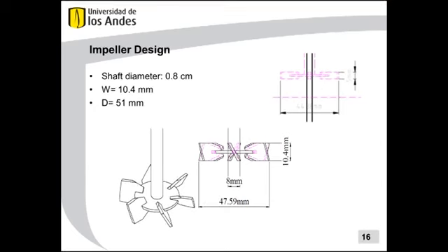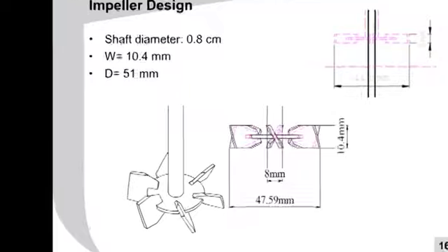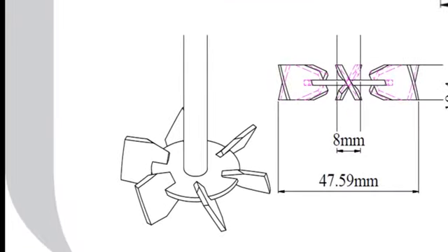The designed impeller had these dimension restrictions, so the geometry designed was similar to the Rushton turbine, but varying some components, like the vane geometry and inclination. Despite the many studies reported, impeller design is still a very empirical process, so we had to be creative. As the vane geometry had more edges, higher shear force is expected.